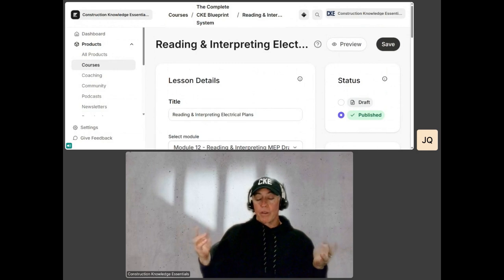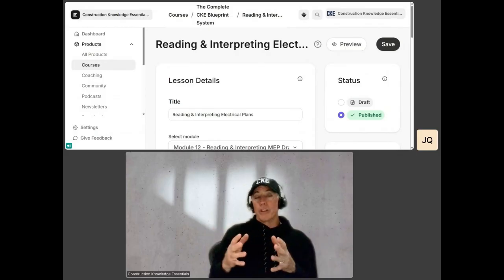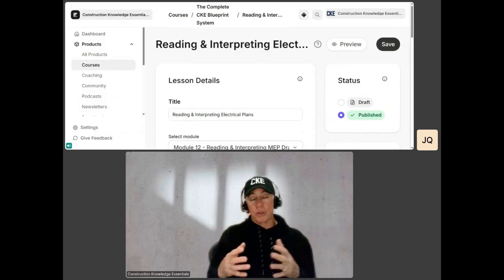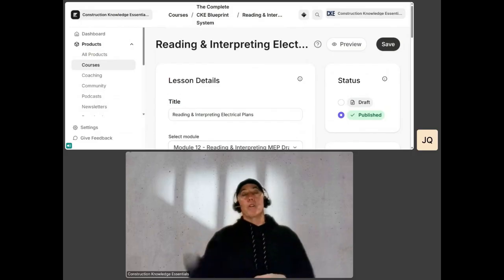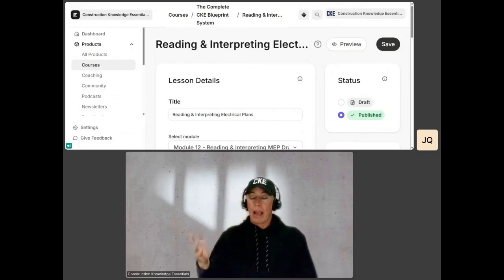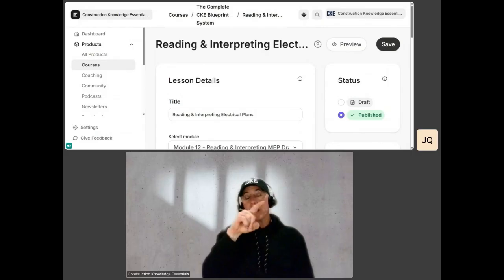So now you go rough-in drywall, or depending on if you're building a shower, you've got your board that you're going to use, depending on what type of board. So there's so many steps that go along with it. I'll call that installer and I'll say, hey, how many days? So now you've got a cascading run of rough-in plumbing, rough-in electric, rough-in walls, and now we're going for finish.